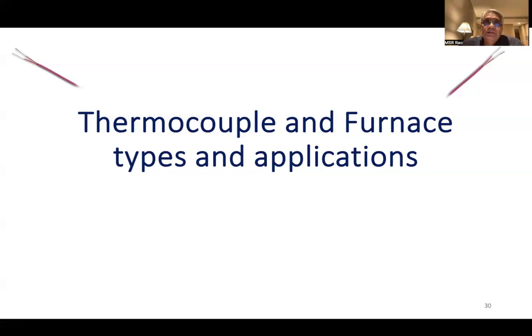I also mentioned that it's very common to use certain heating elements at the lab level for regular heating of compounds, like nichrome, kanthal, silicon carbide, that can take you all the way from 800 to 1600, 1700 degrees centigrade.